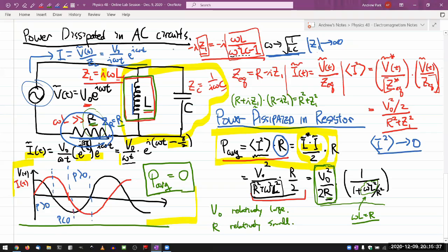If you repeat the analysis for not the total current, but simply for the current through the inductor, then you will find that the I squared value of this is not actually approaching zero. And what you basically have is a circulating current here. Current kind of circulates between capacitor and inductor. And this current never has to cross this resistor, so it doesn't waste any power.